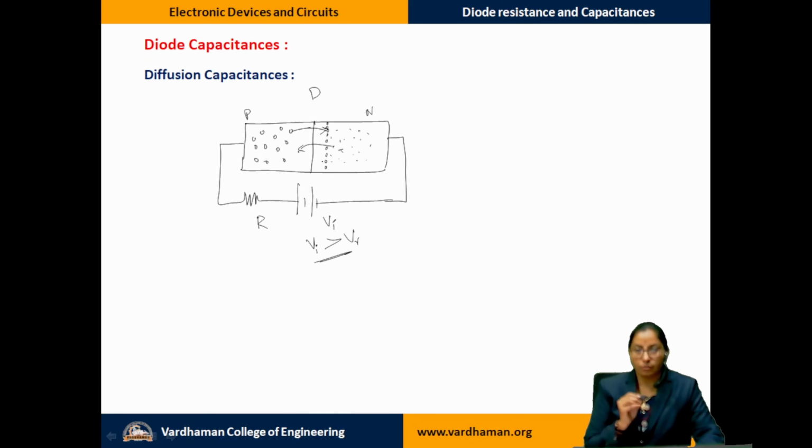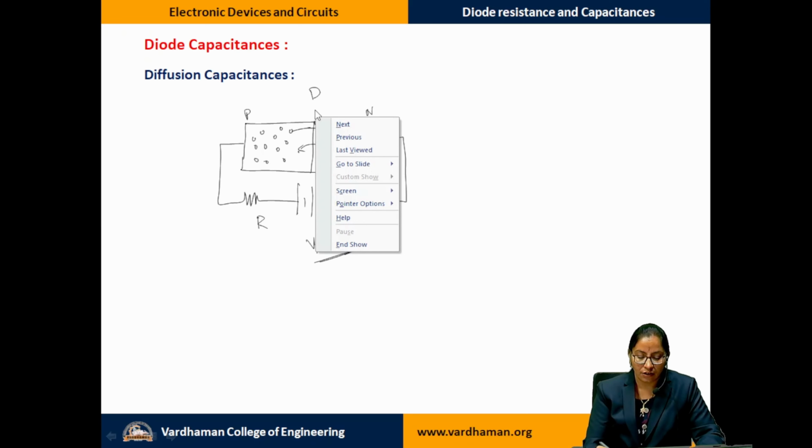They are just moving on from one region to another; the diffusion concept gets completed since they have entered the lower concentration region, and because of the drift the particles tend to move, which implies that the velocity with which the particles move from here to here will be different from that of this movement, so they rush because of drift and diffusion from one region to another. Once they enter the N material, after a certain length traveled, which we call the diffusion length Ln,